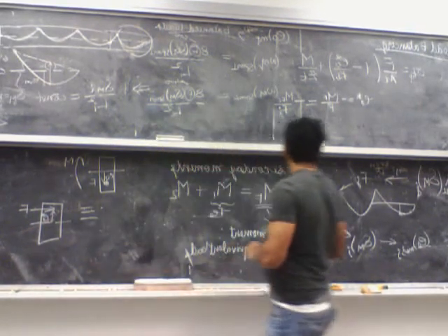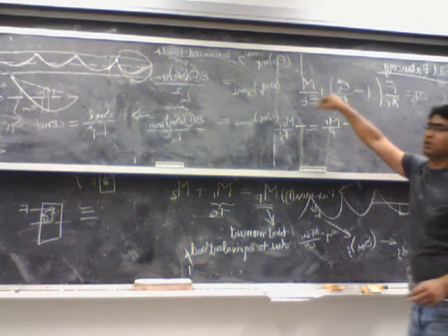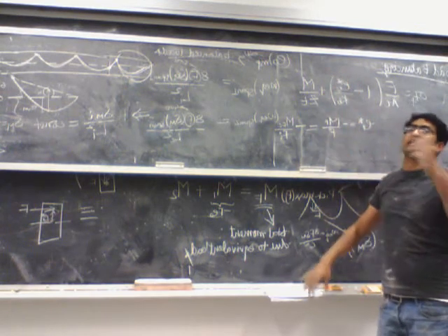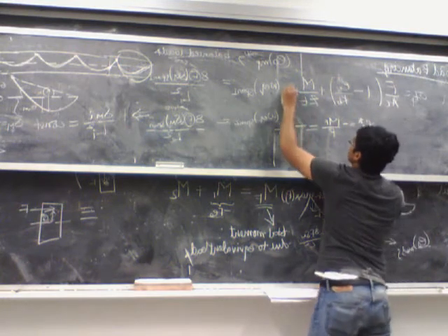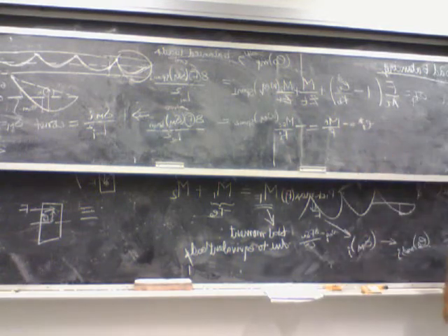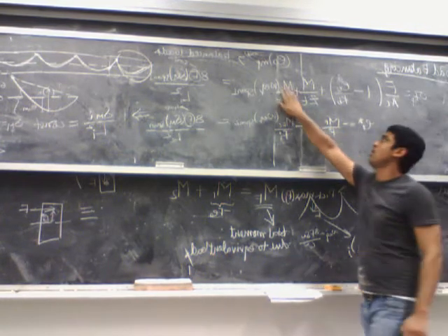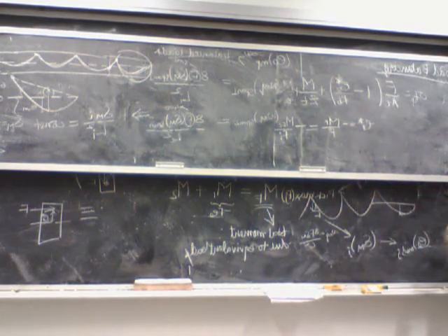So the only difference is your overall equation still remains the same. If you are checking for the top, you use the equation for the top. The only thing is you replace the E naught by E naught star to account for that secondary moment M2. If you don't want to do that, then you have to do this, whichever you like. So either you account for M2 explicitly, or you account for M2 by E naught star. They both do exactly the same thing.